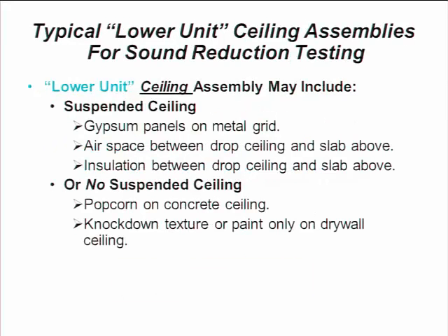Now if we look at the lower unit, when we're talking the ceiling assembly, what you want to know in that test report is what type of ceiling assembly was tested. There's many ways of doing it. You can do it with just no ceiling whatsoever or just a gypsum. Some of them incorporate an airspace into the system. Others include insulation, airspace in that drop ceiling. And the no suspended ceiling is the one that we talk about in certain markets like Florida. That's very popular.